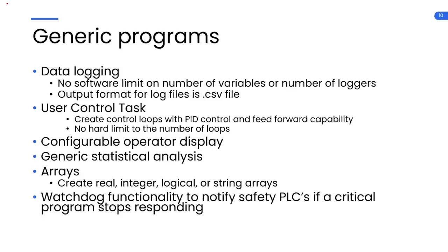Now the watchdog is just a logical variable, but you can tie that logical variable to a digital output on your system, which could be tied to a safety PLC, and that safety PLC can actually be what says, oh, CyFlex has stopped responding on a critical program, and then the safety PLC can be hardwired to put your automation system, your test cell, your air handler, whatever it is, in a safe state.